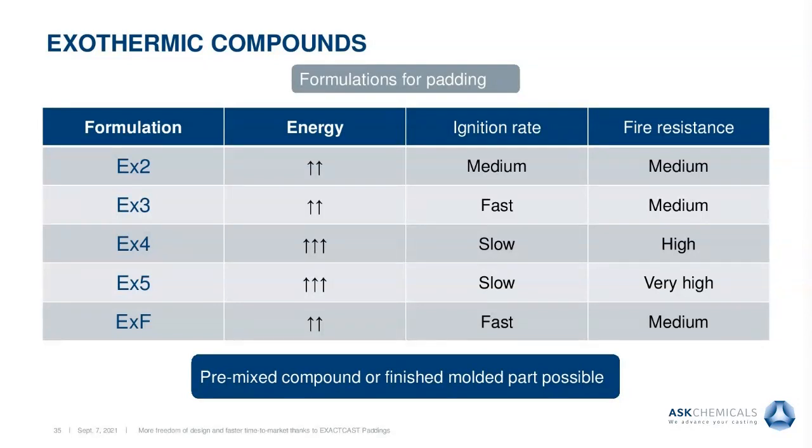This depends on your casting alloy, your size of the casting, and some other things. But please feel free to contact us about which could be the best one for your casting. We will help you here. We strongly recommend, of course, in ductile iron to use a fluorine-free formulation to avoid any graphite degeneration on the casting surface where it gets in contact with the melt. This is strongly recommended to not get in trouble with your graphite formation.